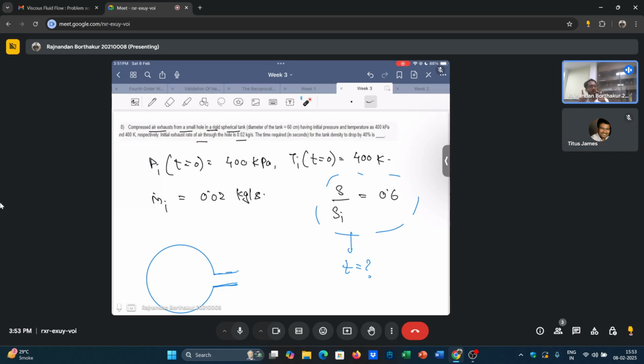And you also need to understand that the mass flow rate at which the air moves out is also not a constant, and it will inevitably be a function of time. You can understand it something like this. Let's say you are filling a balloon. The only difference between a balloon and this problem is that the volume of the balloon would also change. But here, let's say you are filling up some kind of a rigid balloon, and then through some opening you are allowing the air to pass through, which means that at initial time air would move faster.